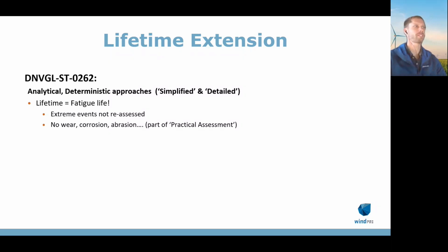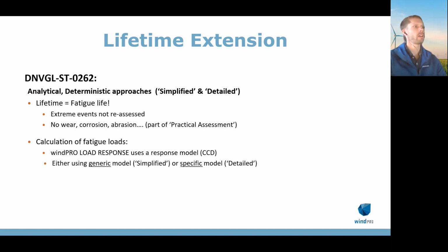One thing I'd like to emphasize here, when I say a lifetime, it is always implicit here that we mean fatigue lifetime. So it's lifetime within the calculation framework of fatigue. Because in the standard, there is no requirement to assess extreme winds, for instance, because they were assessed when the turbines were installed, and that will still hold. The analytical calculations do not account for wear, corrosion, or abrasion. That is all a part of the practical assessment where the turbine is inspected from the outside. The lifetime here means fatigue life.